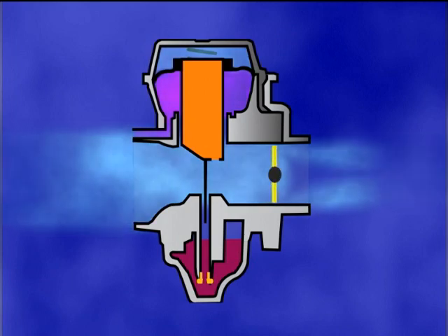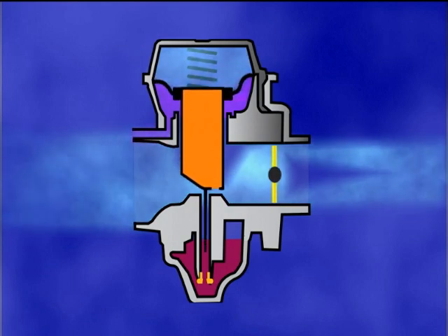When the throttle plate is closed, airflow decreases and pressure differences between the top and bottom of the vacuum slide assembly begin to equalize, causing the slide to move downward. While not directly connected, the throttle plate and vacuum slide work in conjunction to control engine speed.